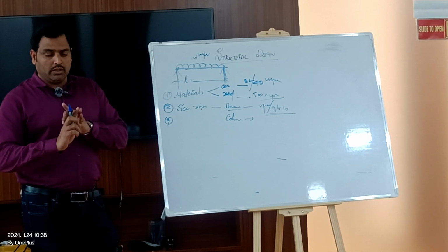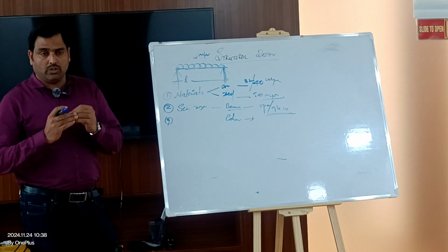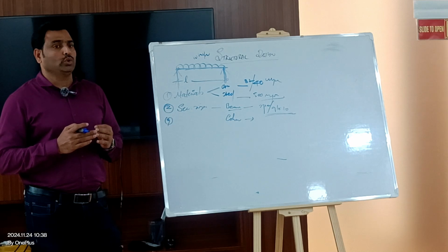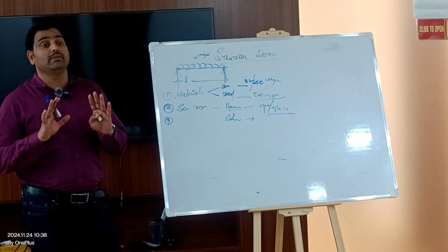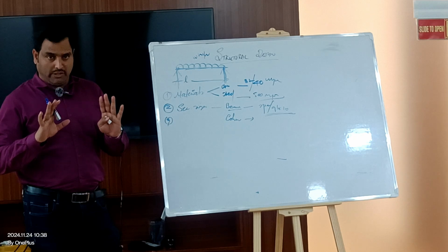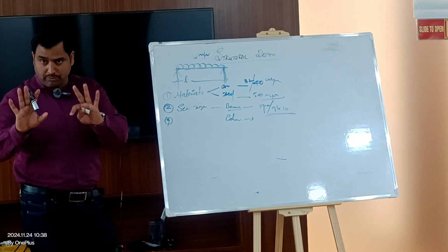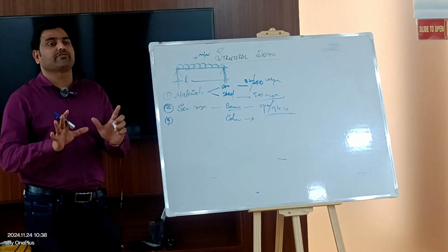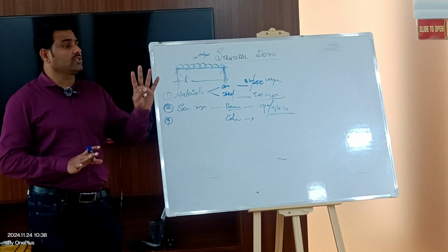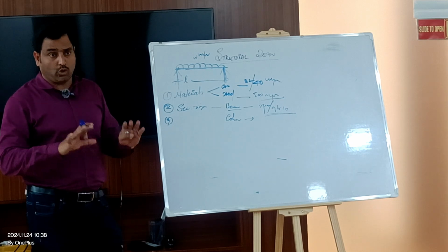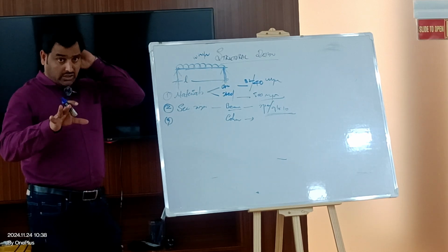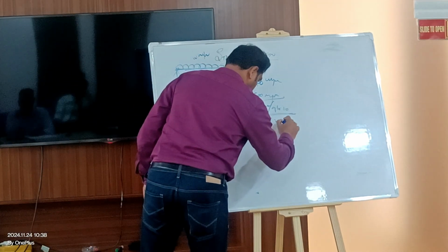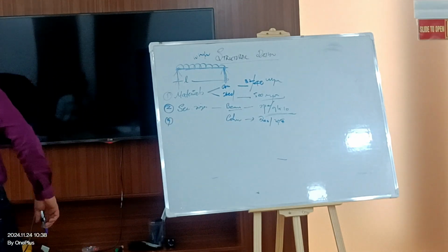DDA and DM, it's not a mandate rule, but they have given a verbal confirmation that we should not use columns less than 250 millimeter in width, even for villas. Before they were accepting 200, but now some engineers keep a different opinion, so they want not less than 250 millimeter width. I'm talking about the villas. They were rejecting the points. It depends on the engineers. But still, I will write 200 to 250.